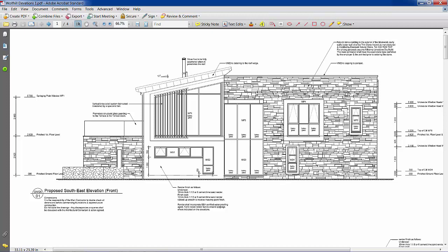The position of the windows and the position of safety glass down here, but no safety glass in these ones, is also clearly noted. And we have a brise soleil system which comes along on this side of the elevation. There's stonework on this back element of the building, and then stonework on this two-story element towards the right hand side of this elevation. And again, safety glass and openable windows are noted in appropriate places. We have some annotations in relation to the stone cladding and what way the roof or the wall is finished at roof level, so there's a parapet there.